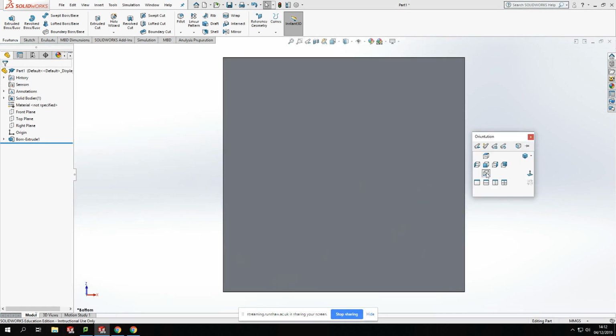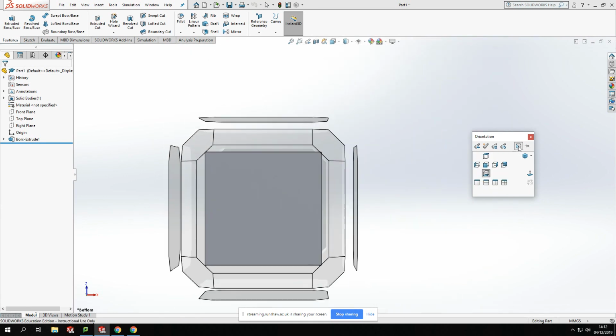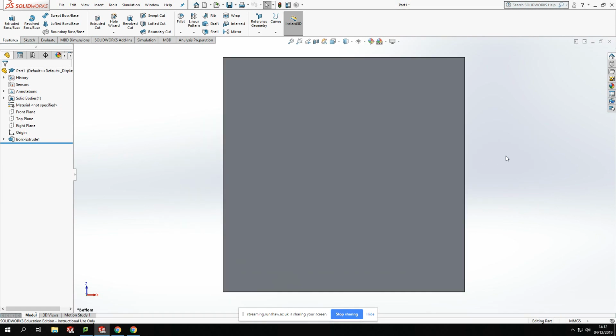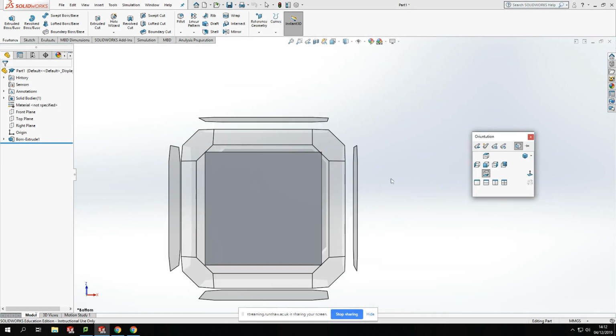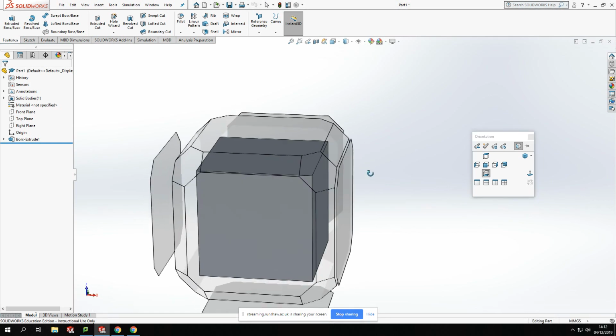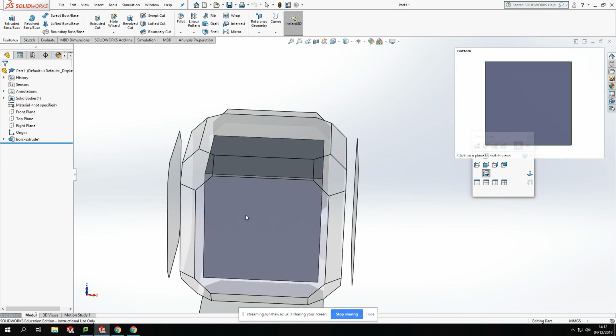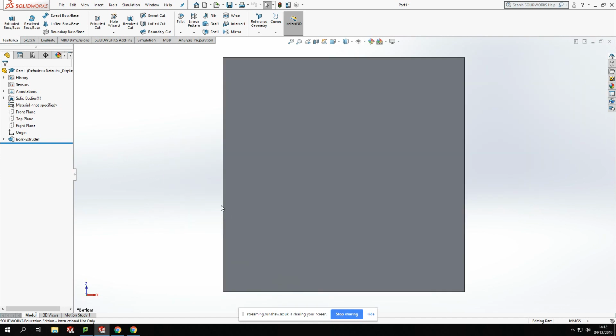Now, I can also use the space bar to set up a view selector as a quick selection on my keyboard. So if I now press space, it will come up as a view selector, and I can manipulate that round. And if I click on any of those sides, it will automatically make me normal to that face. In other words, bring that face straight on the screen.